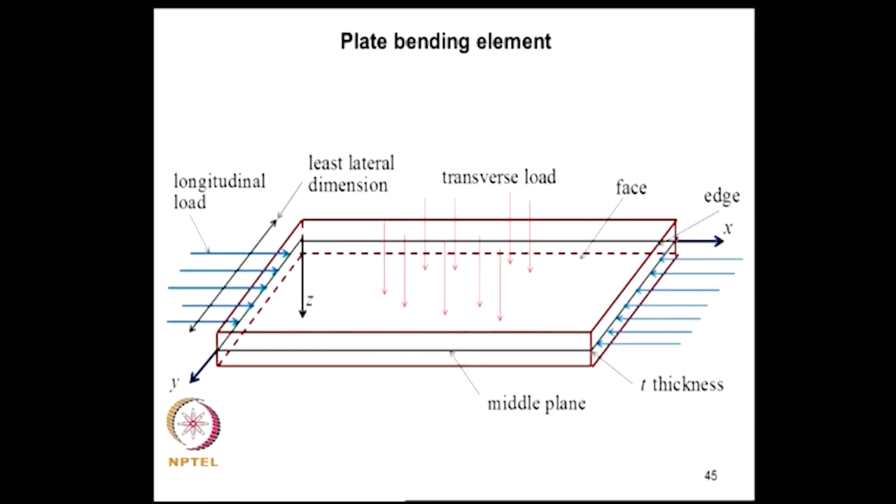Next, what we will consider is this plate bending element. We have been considering only the action due to transverse loads. Now, in problems of shells, there can be simultaneous presence of axial loads as well as transverse loads. So, in shell structures, the element need not be flat initially, that is one of the assumptions, if you recall, we made when we were dealing with plates. But if we agree that a curved surface can be represented by using flat elements like this, we can still use this theory that we have developed.